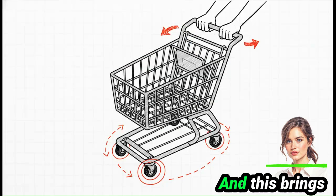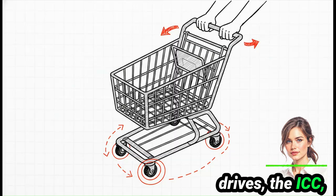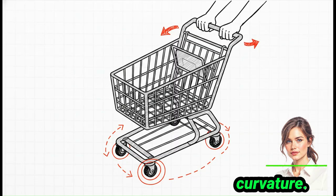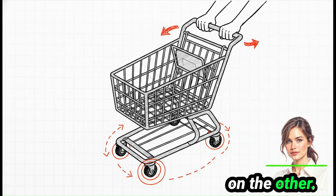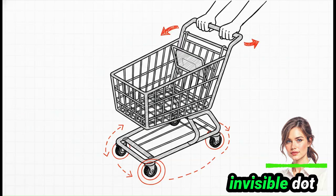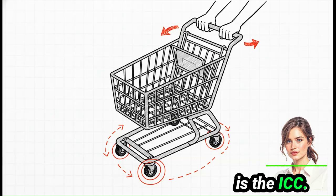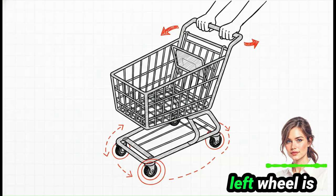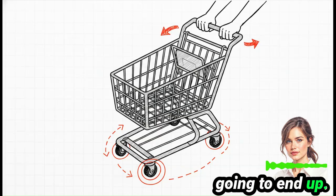And this brings us to a super cool concept for differential drives, the ICC, or Instantaneous Center of Curvature. Imagine you're pushing a heavy shopping cart at the grocery store. To turn it, you pull back on one side and push forward on the other. Notice how the cart spins around this invisible dot right between the back wheels? That dot is the ICC. By doing some quick math on how fast the left wheel is spinning versus the right wheel, we can plot exactly where our robot is going to end up.